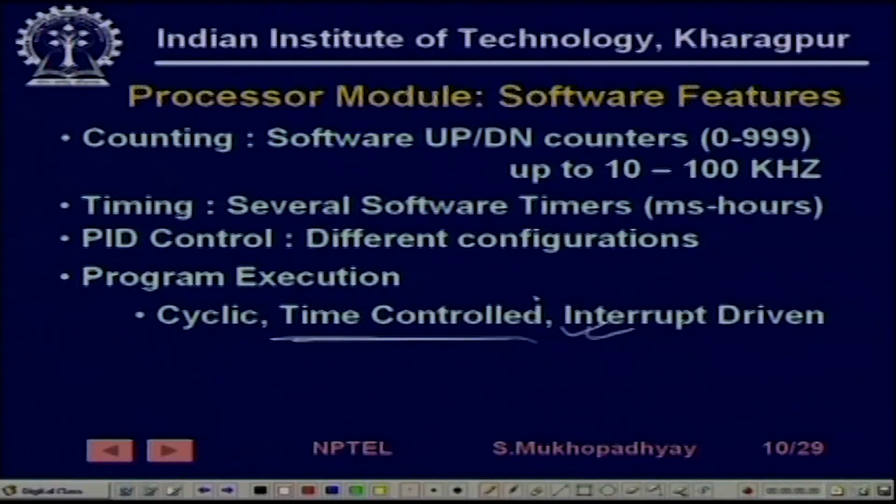There are some tasks which can suddenly occur, like failures, which once they occur are not taken into consideration of the regular computing flow, but once they occur they are required to have very high priority, and therefore they have to immediately get the attention of the processor. So, such tasks are sometimes coded in the interrupt driven execution mode. So, whatever the processor was doing, it will be interrupted and this requirement will be catered to.